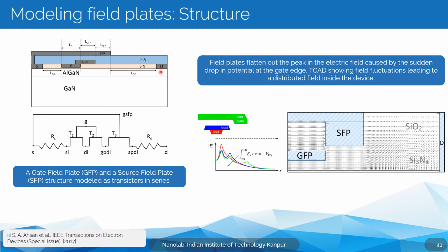So that voltage, say for example 600 volts, is almost entirely carried up to this gate edge. And then if the gate is, say, at a voltage of -2 volts, then the entire 600 plus 2, which means basically 602 volts, the entire 602 volts drop is felt across this junction.